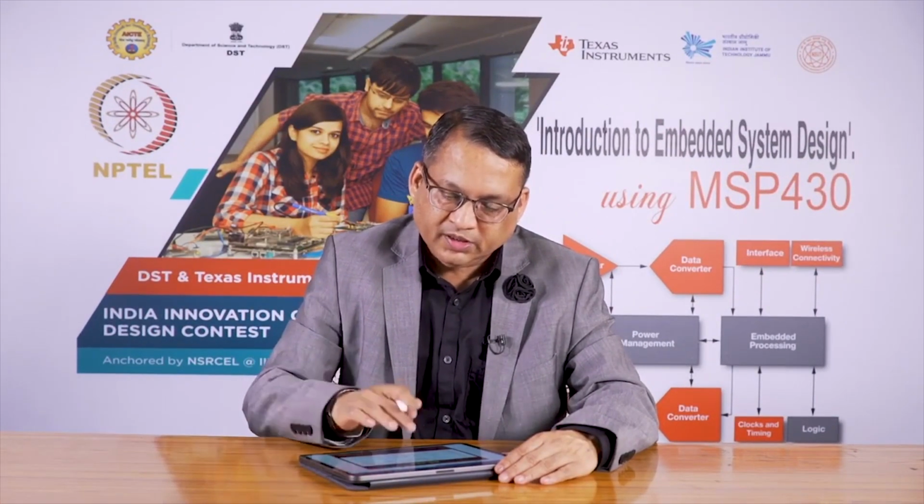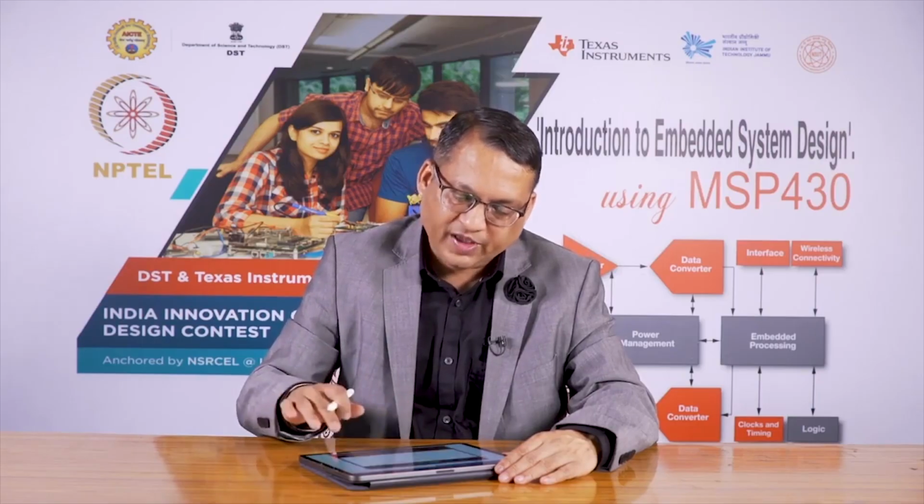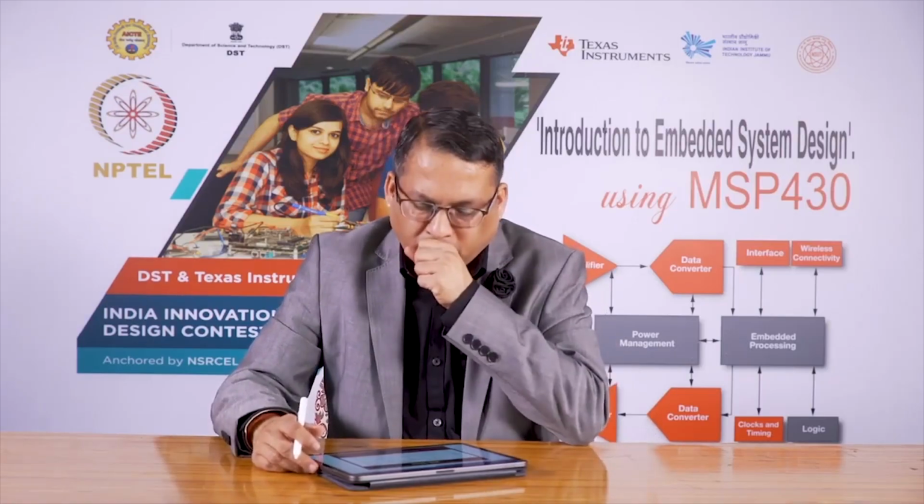Now, in all these discussions till now, we have seen that there is only one transmitter and one receiver, that is, there is a transmitter on one end and receiver on the other, and the other side has a transmitter and receiver. This allows for full duplex communication. And what if you wanted to communicate between more than two devices? Like here we have device 1 and device 2, what if I wanted to have one more device? Using these protocols, it is not possible, but there is a modification, and there is a new method, a different method called RS485.